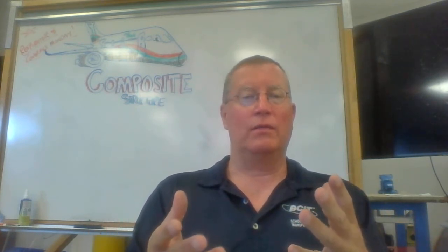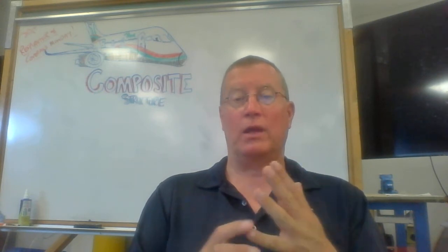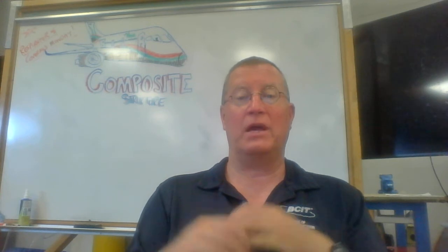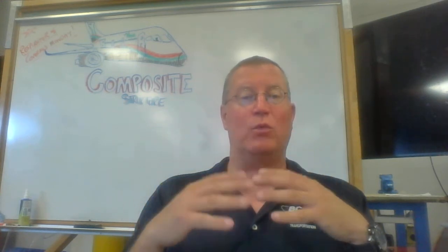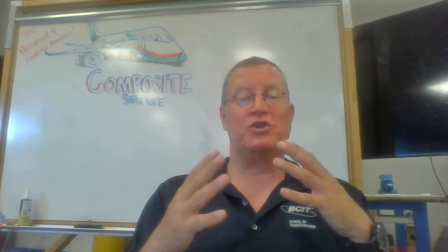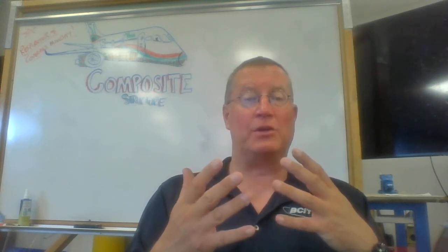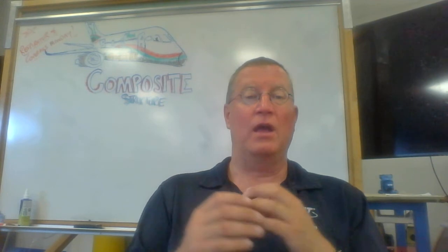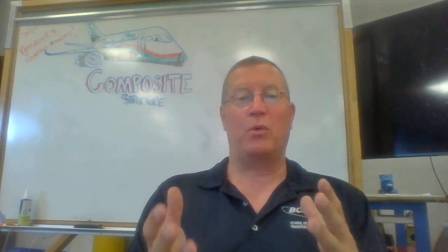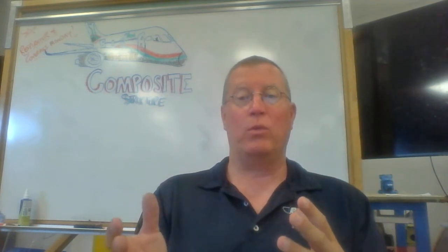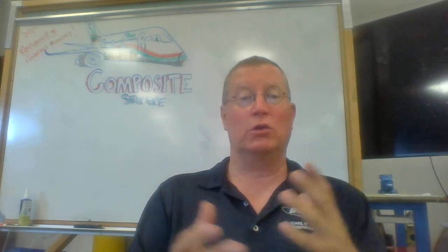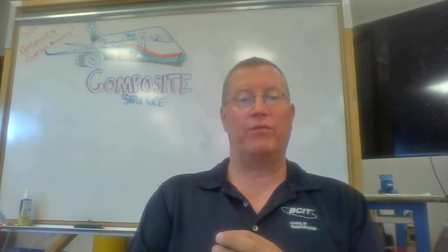And so how are we going to know? Well, the biggest thing again is going to be our visual. Can we see the damage? In a lot of cases it's going to be super hard, because with that flexibility it will flex, return to its shape, but have a sustained damage, right? And so detailed inspection is the big thing. So around access points on the aircraft where people will be working, where equipment will be working, having a really good look at those components on the airframe.